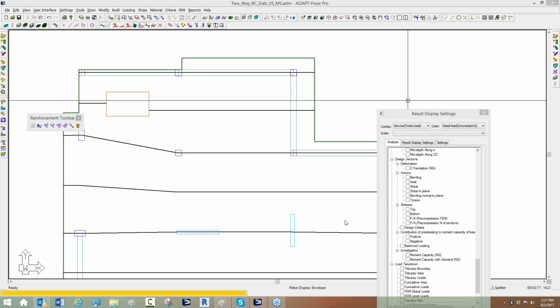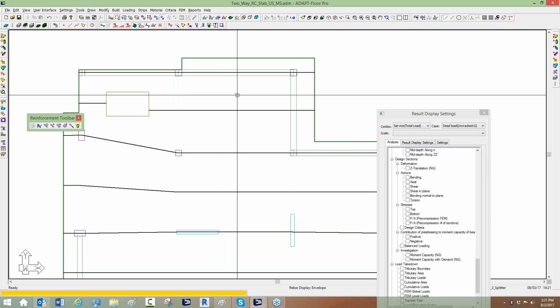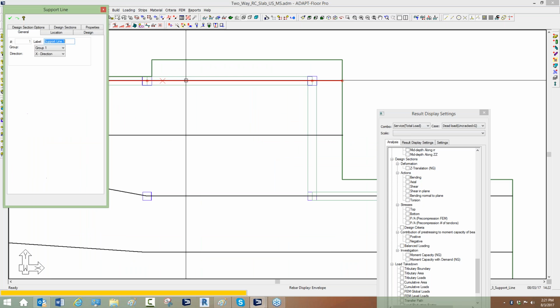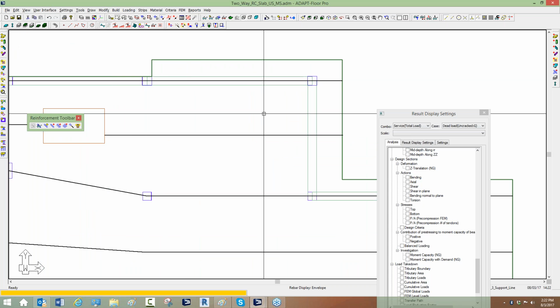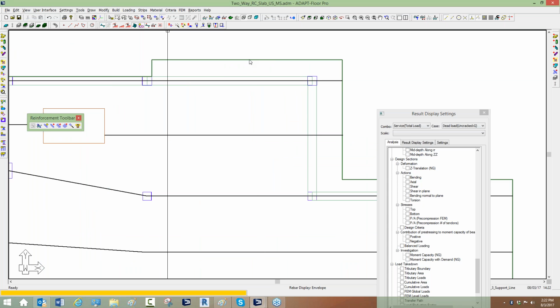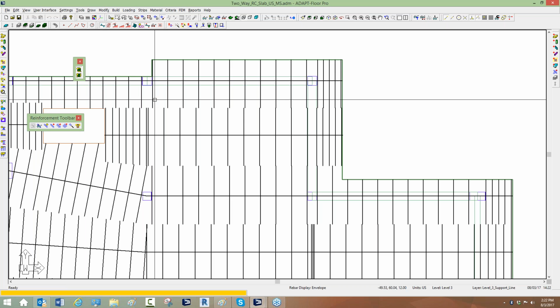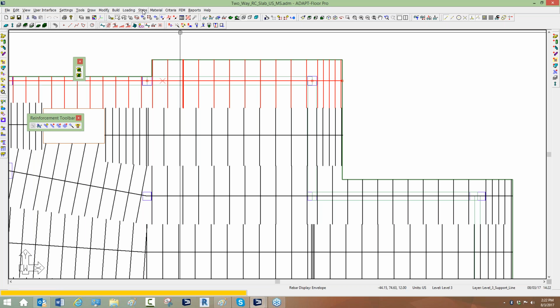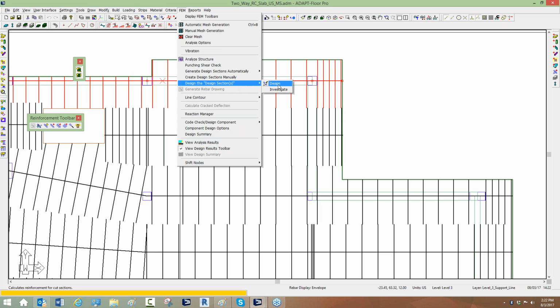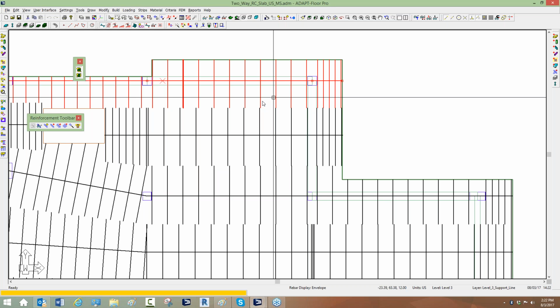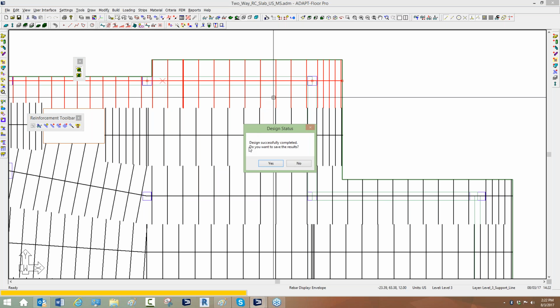Shear in beams, yeah, the program does design for shear in beams. So take this design strip up here, for example. If I go ahead and generate that design strip again, and I design this one particular strip, whenever you have a beam design section, the program will design for one-way shear.